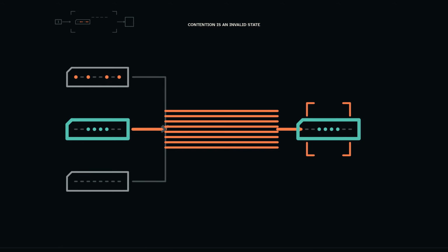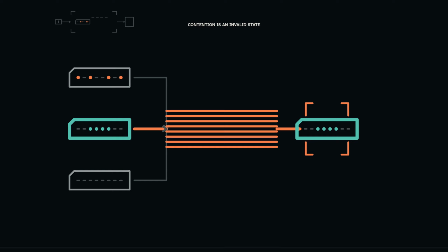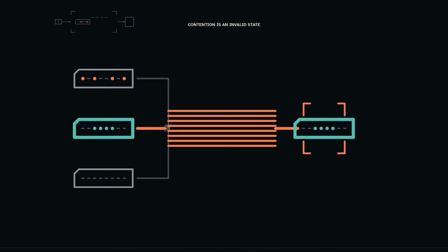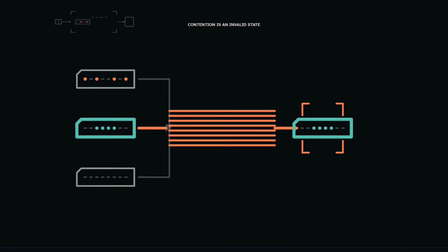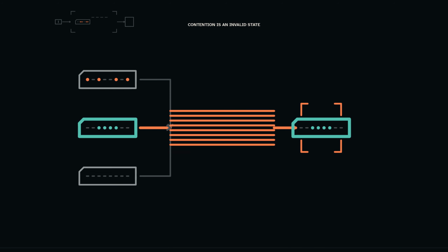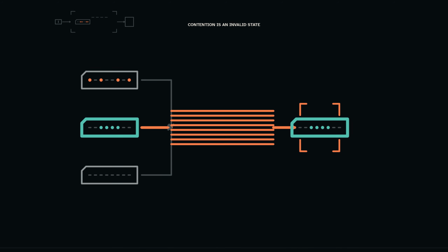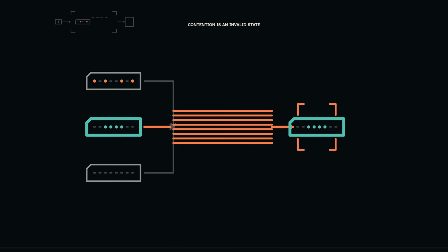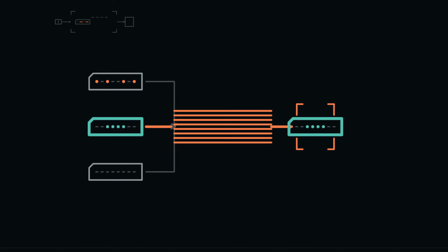At the edge, R1 captures the 8 classified input bits together. After the edge, R1 holds hexadecimal 3C even when R2 is disconnected and the bus becomes inactive. Source drive, route settlement, and destination capture are 3 distinct events. The before and after ledger keeps them from collapsing into one unexplained motion.